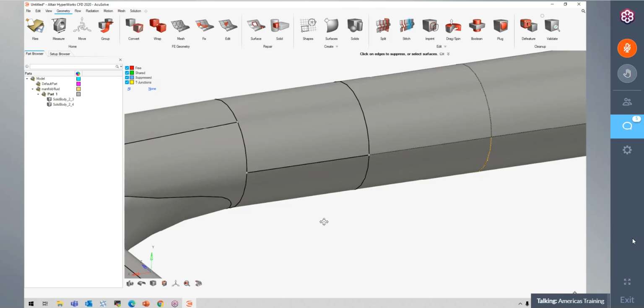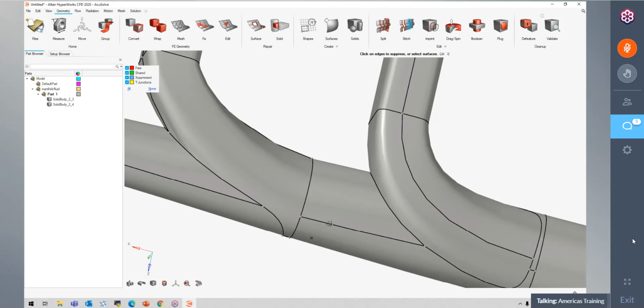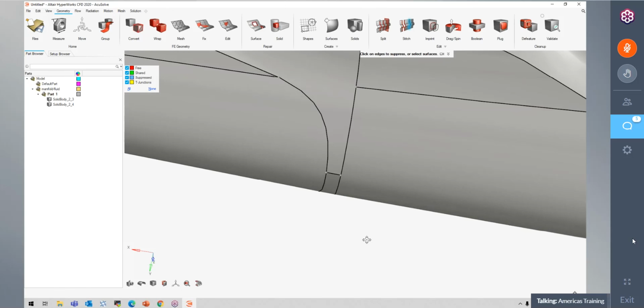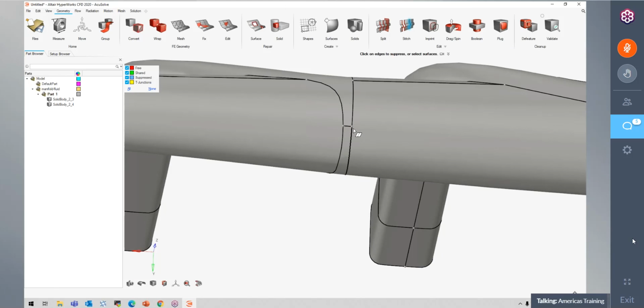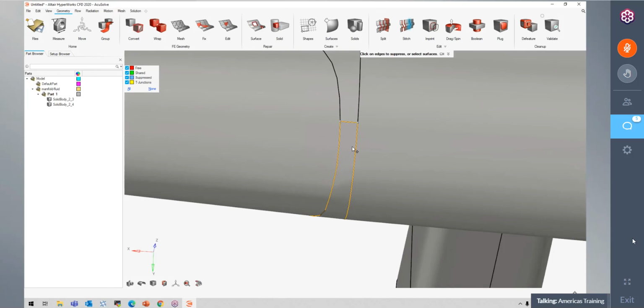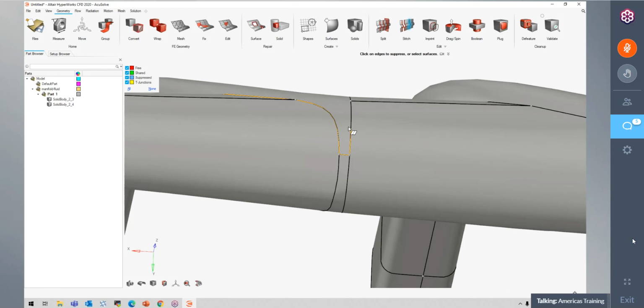And the reason why that's important is because sometimes when you start looking at your model, if you go into regions like, for example, down here, you'll have some surfaces that are very, very, very small, and that will cause some problems with meshing because they're just so tiny and the mesh is trying to fit elements in that region. So sometimes it's important to remove some edges.